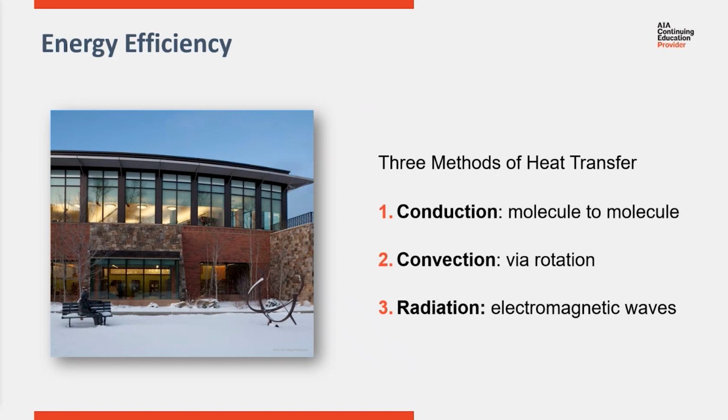So glass and glazing is being utilized more and more as a substantial percentage of the building envelope. For that reason, it's critical to effectively evaluate their contribution to the energy performance of the project. From a design perspective, it is important to understand that in colder climates, the building is losing heat through the exterior wall, and in warmer climates, the building is gaining heat through the exterior wall.